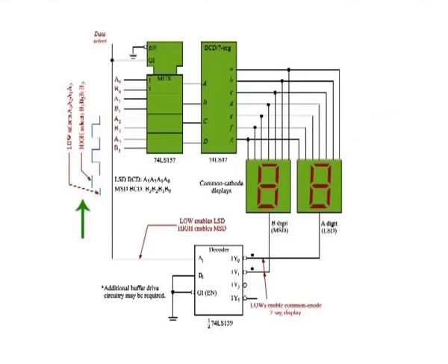When the data select line goes high, the B bits are passed through to the input of the BCD to 7-segment decoder. Also, the 74LS139 decoder's 1 output is activated, thus enabling the B digit display. The B digit is now on and the A digit is off. The cycle repeats at the frequency of the data select square wave. This frequency must be high enough, about 30 Hz, to prevent visual flicker as the digital displays are multiplexed.